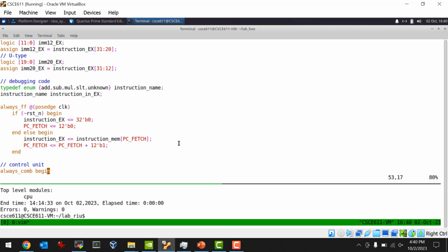But RISC-V does not use all zeros for the no-op. RISC-V uses an add instruction, but the problem is the add instruction has a function 3 code that is like 0, 1, 1. So I just thought we might want to revisit that. It doesn't matter for you guys, because you can just put a line in your control unit and treat this as a no-op. So it's not a big deal. I just thought of that now. That's one oddity that's come up in the past, but that's meant to be a no-op.